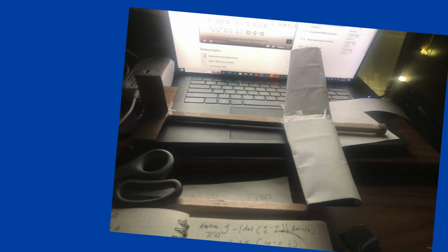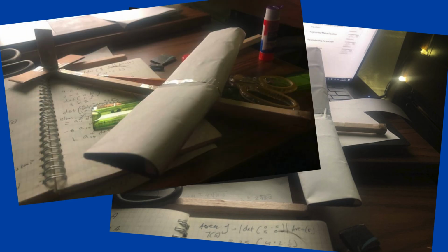I created a balsa cardboard prototype out of scrap pieces that was a scaled down version of the final design. In this prototype, I would have basic square horizontal and vertical stabilizers made out of cardboard and test out slightly tapered wings with a paper airfoil. The wing would be mounted at a 2 to 3 degree angle of attack.